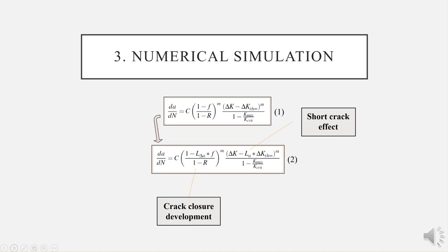Now let's try to build a computational model to numerically simulate a situation that is similar to those in the experiments discussed before. We will be using a complete initiation and propagation model, which I will not explain in much detail since that has already been done multiple times before by authors such as Jaime Domínguez, Carlos Navarro, and Jesús Vázquez. In a nutshell, typical initiation and propagation models require one to choose what's called the initiation length, which is the length the crack has by the end of the initiation phase.